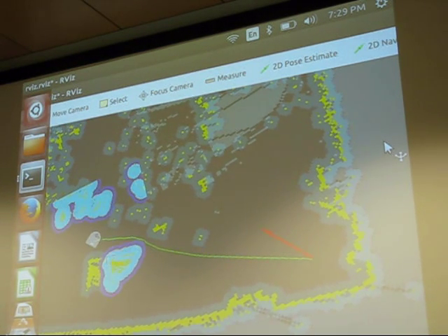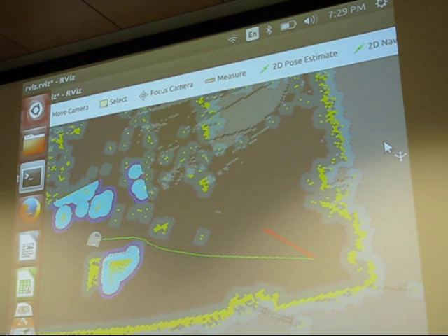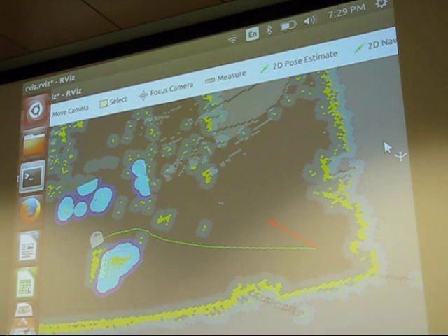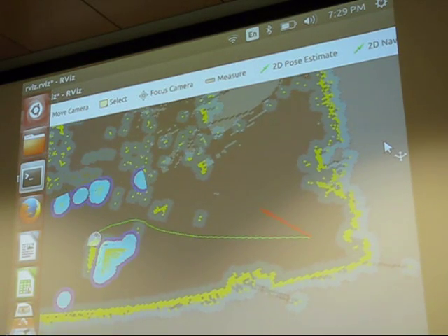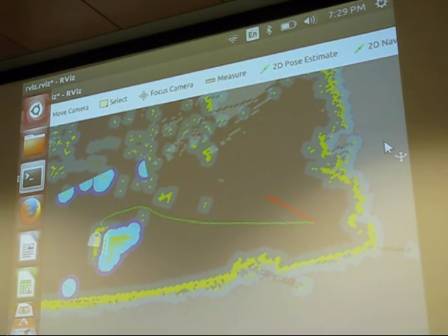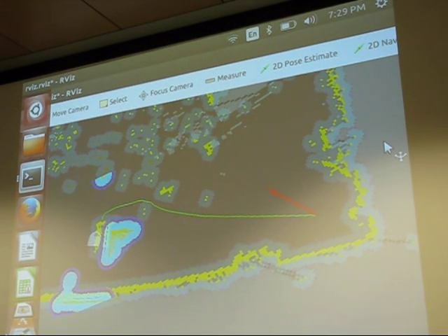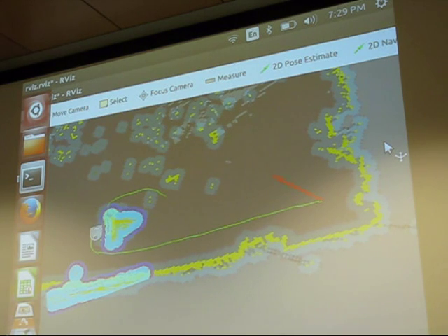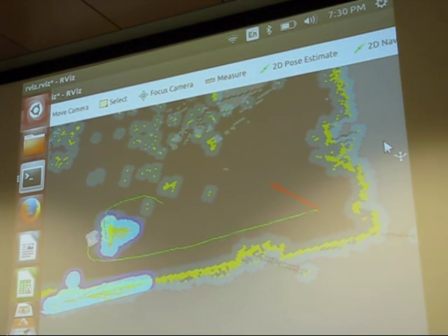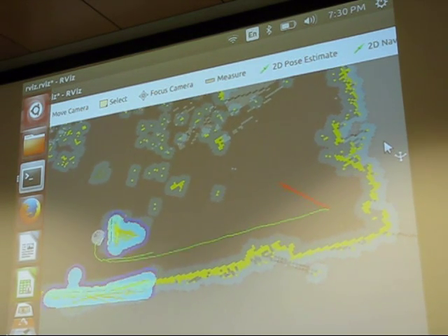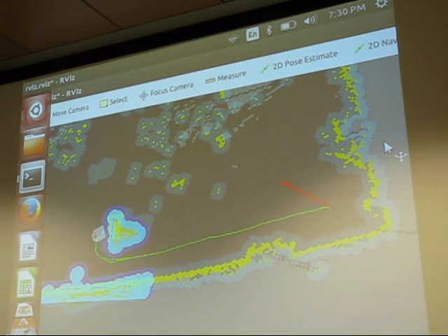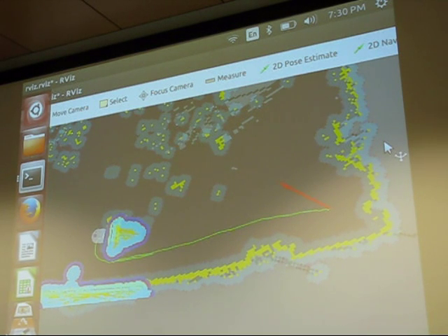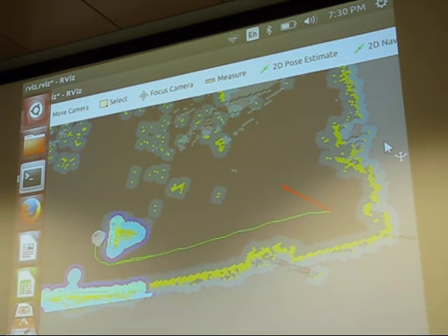Excited, huh? Question. Shoot. What's the LiDAR sensor that you're using? This is the Neato robot vacuum cleaner. It basically has a laser and an imager, and it uses trigonometry to discern the distance of the obstacle. It spins at 5 hertz. It takes 360 snapshots per cycle. And again, the Bot Vac, I can't say enough about the Bot Vac being a great ROS trainer, as well as a floor cleaner.